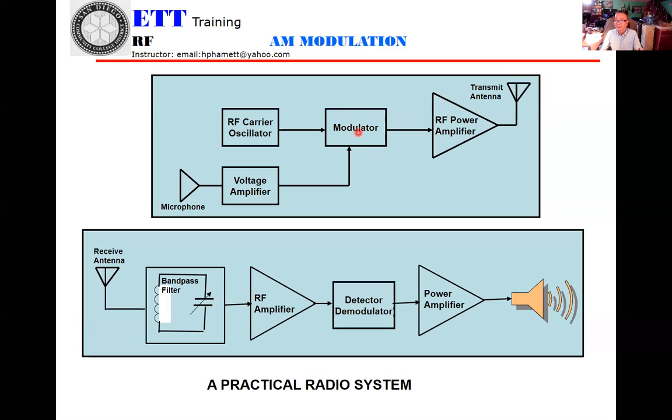However, the question is, will that amplifier be linear or non-linear? It is non-linear. The thing is, that amplifier inside here can change the gain without you touching it. An audio amplifier is linear: if you want to change the gain, you have to change the component.